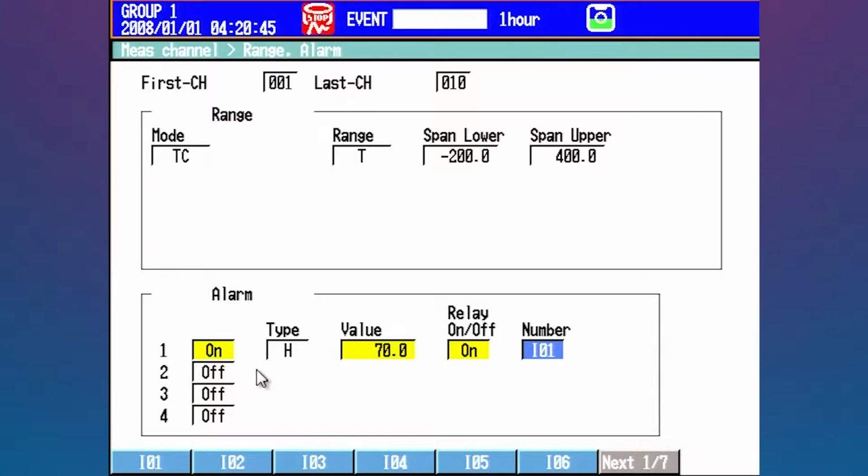These will show up if you don't have the hardwired relays on the back. So just make sure that if you take a look at your data plate in your suffix code, you'll see stuff like A1 or A2 or A3. That would designate that you bought your units with the actual alarms. Okay, so this is where you can essentially pick which relay you want to go. 1 through 6, I think you can have somewhere 12, 24 on this unit.